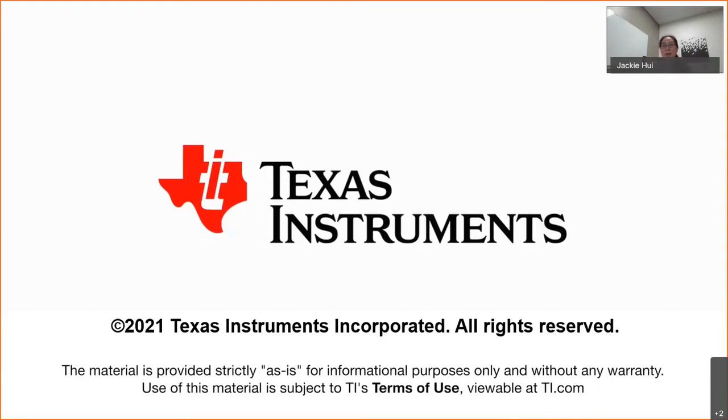And with that note, another thing you can consider during the debug is, if you suspect that your Bootstrap circuit has a problem and that's what's causing the issue, one debug approach is to remove your Bootstrap components and actually power it with, say, a floating supply, for example, a battery. That way, you can see if you're still having a similar damage or similar issue. If not, then you know it's a component in your Bootstrap circuit, and you can start to isolate the problem.